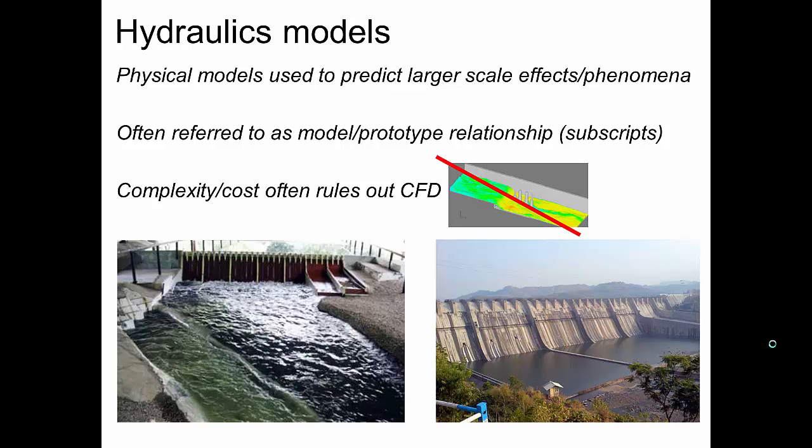Now the flow in this is really complicated, and we can't always use computational fluid dynamics, which is a common sort of tool in this area of civil engineering. If the flow field becomes too complex, the numerical models break down, and it's very difficult to have a lot of faith in the answer. They obviously look very nice, but they can be overstretched.